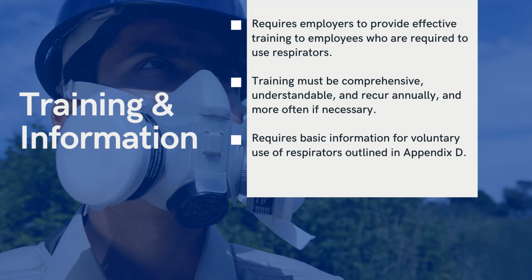Quantitative fit testing uses a method of testing that utilizes specialized equipment, such as a PortaCount, to measurably test the amount of leakage around the seal. Quantitative methods can be performed by ambient aerosol, controlled negative pressure, and generated aerosol. Employees using a tight-fitting facepiece respirator must be qualitatively or quantitatively fit tested prior to initial use, whenever a different respirator is used, and at least annually.